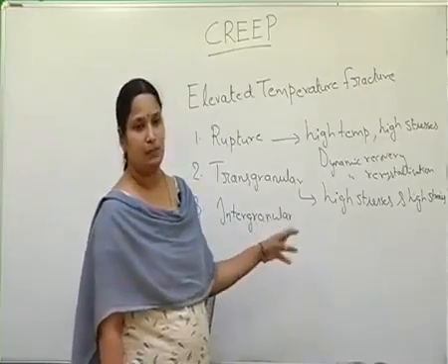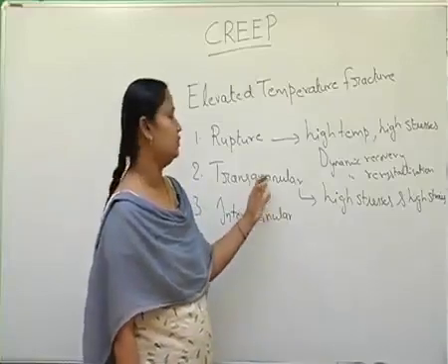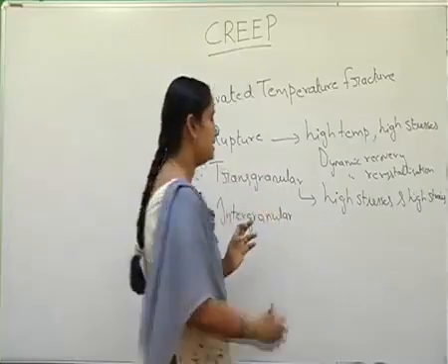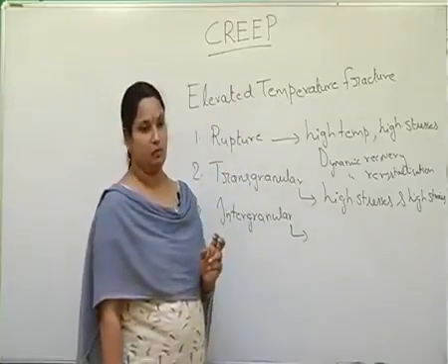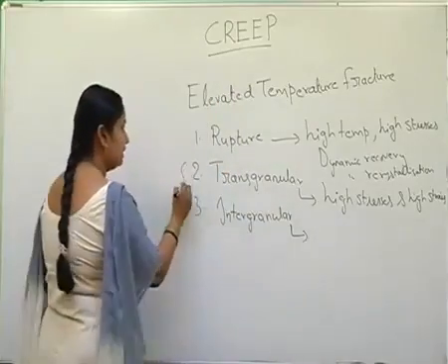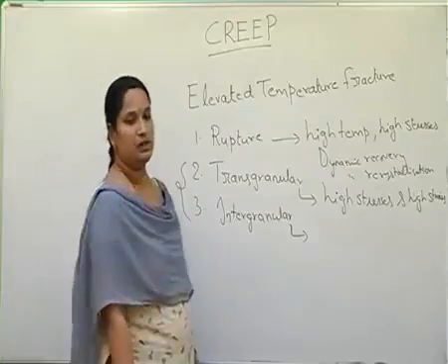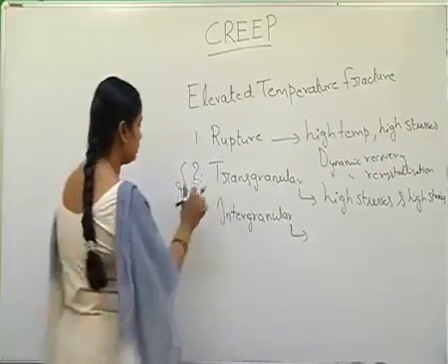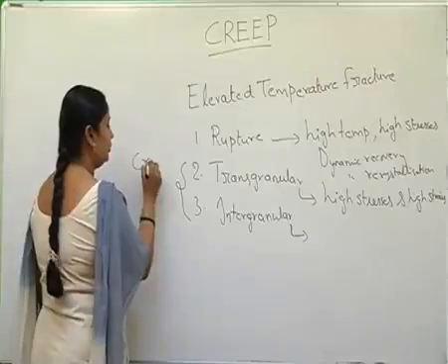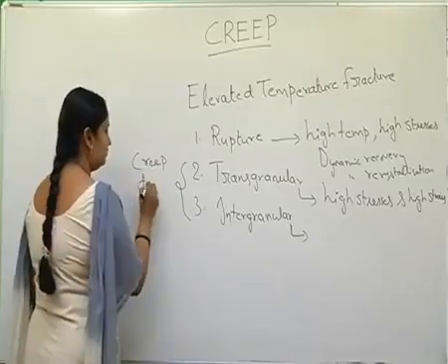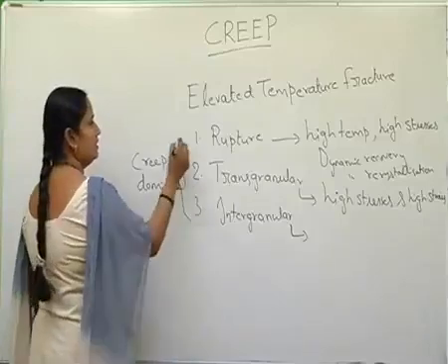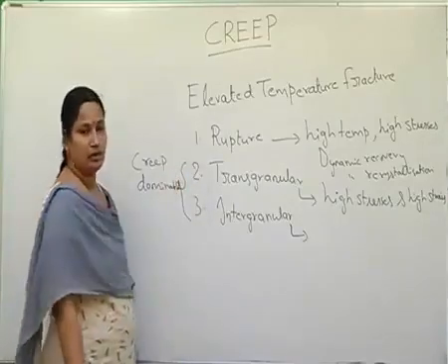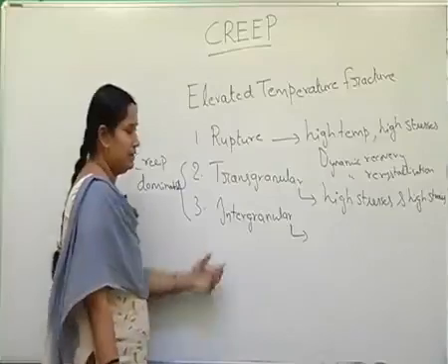Since transgranular fracture is a creep dominated fracture, and intergranular fracture is also a creep dominated type of fracture, we shall discuss these two elevated temperature fracture modes. These two are creep dominated fracture modes, whereas rupture is not a creep dominated fracture mode. And in the case of